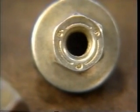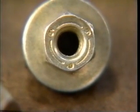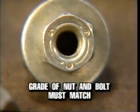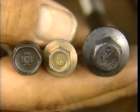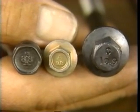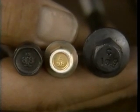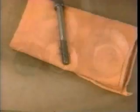Hex nuts are graded in the same fashion. The number of lines or marks stamped into the surface indicates the grade. Always make sure the grades of the nut and bolt match. Metric fasteners are rated in a manner similar to U.S. standard bolts. Instead of lines or marks, they have numbers stamped on them in a common range from 4.6 to 10.9. The higher the number, the stronger the fastener.